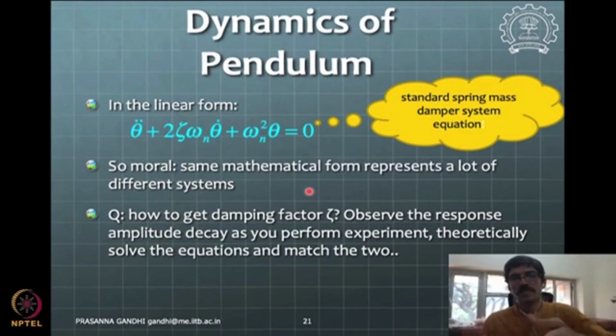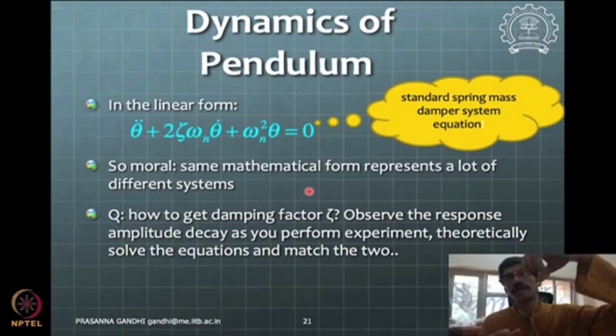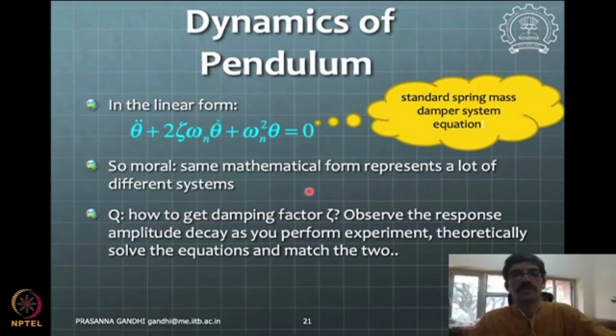But one can see that if the disk is not there, only the head is there, and in place of the head you have a big mass attached, then in the vertical plane this will act as a pendulum kind of system, and at the back side you had the coil and the magnet. That is the actuator which is giving some torque on this system. That is a kind of pendulum system that we can have. So that is one of the actuators possible in the direction of theta.